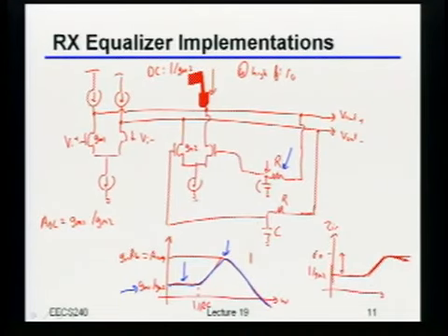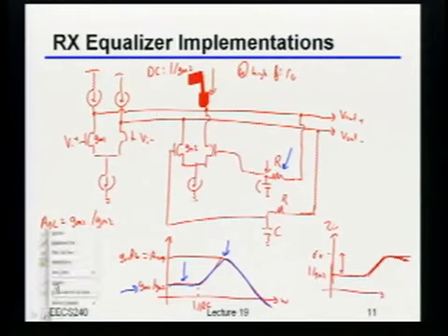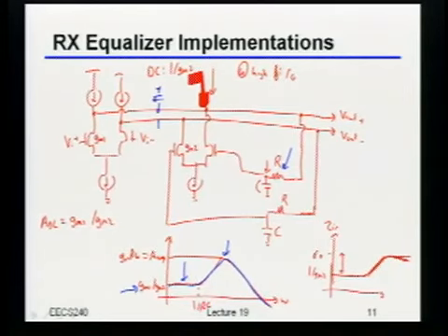Does the feedback amp need more bandwidth than the main amplifier? Yeah, I think their bandwidths are actually basically the same, right? Because they're driving the same capacitive load. There's the same cap sitting out on the drains of both of those guys. So I think their GM over C is actually just set by the ratio of GMs. There's something even simpler than this.